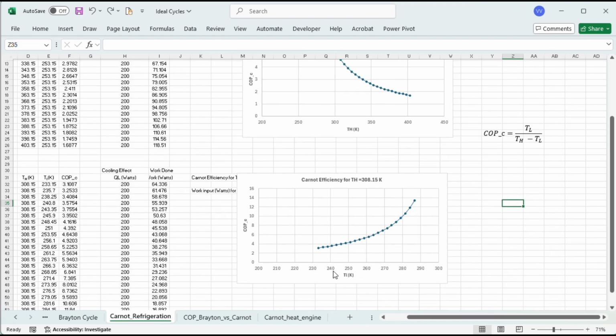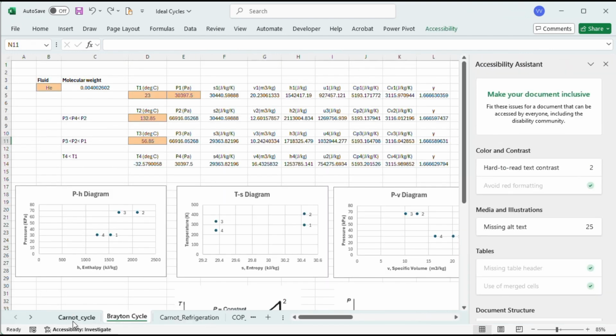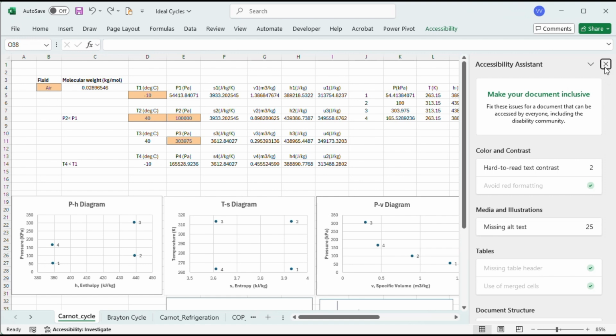And the place where you're removing heat, so let's say if you're removing heat from a room at 40 degrees C versus 20 degrees C, you will be more efficient when you're removing at 40 degrees C compared to at a lower temperature. Okay, so higher the temperature of the cold place from where you're removing heat, the better the efficiency. Okay, all right. Now let's look at some actual Carnot cycle calculations here.